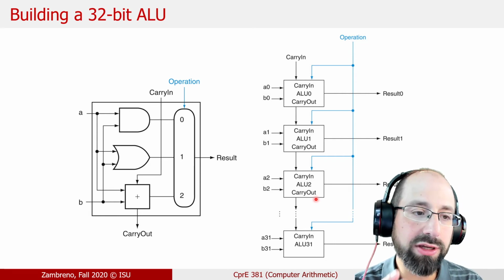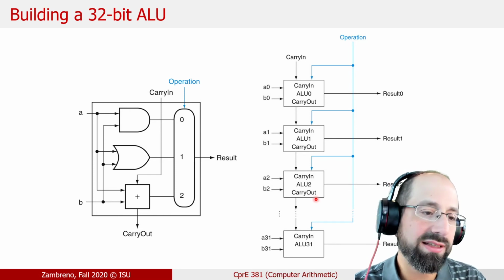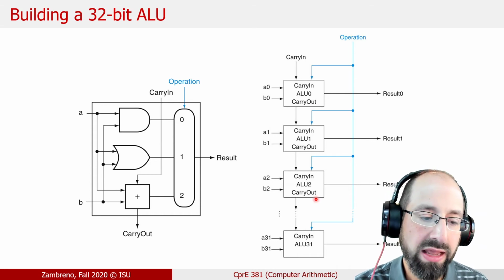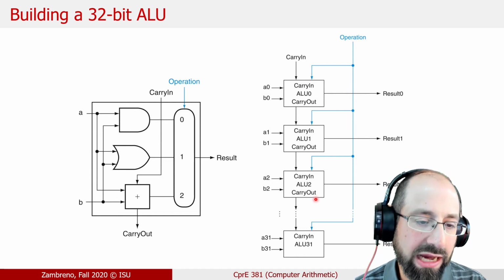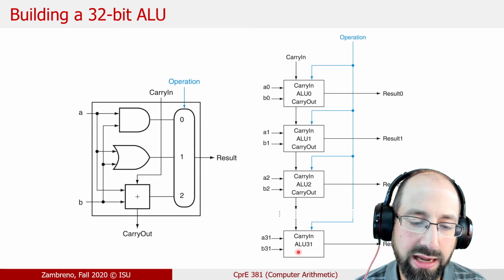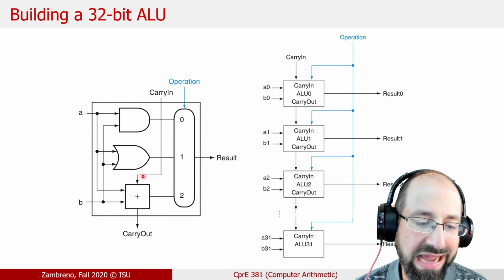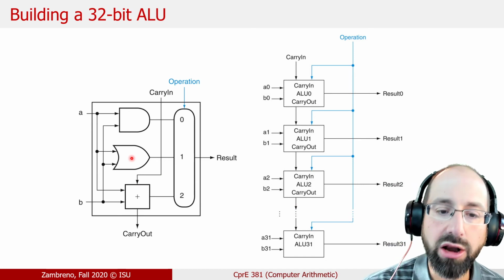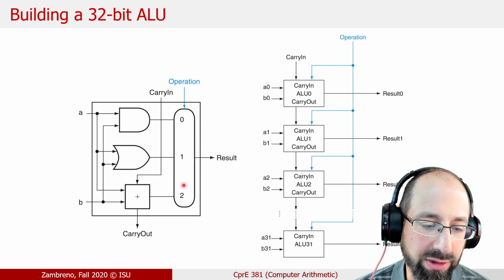It tends to be looking at our current architecture, our diagram generally, and determining what signals need to be muxed out and changed based on what that new instruction is supposed to be doing. So this applies for our ripple carry design, even though as we look at that carry path, this black line going from carry in to the final carry out at the very end, that carry path is really only relevant in the context of the adder part of that circuit. The AND gate and the OR gate don't engage the carry path at all, and those should all be zeros for the design that's coming back out.